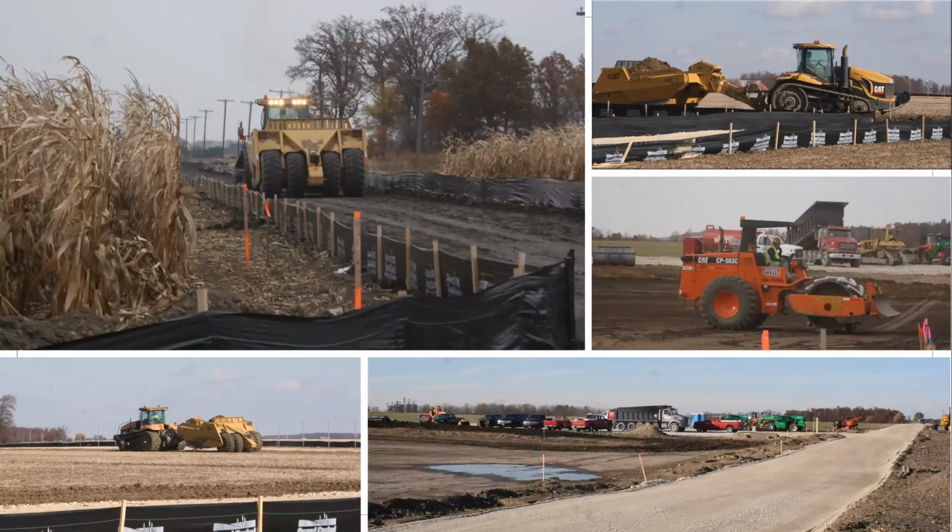The next thing that you really start to see is some of the site grading. For the most part, most of the site is not necessarily graded. When you look within the alleyways at the solar panels themselves, the racking system pretty much follows the natural contour of the land, which was relatively flat. We had slopes of less than, I think, 2-3%. So there's not a lot of grading, but with that said, there's certainly some.